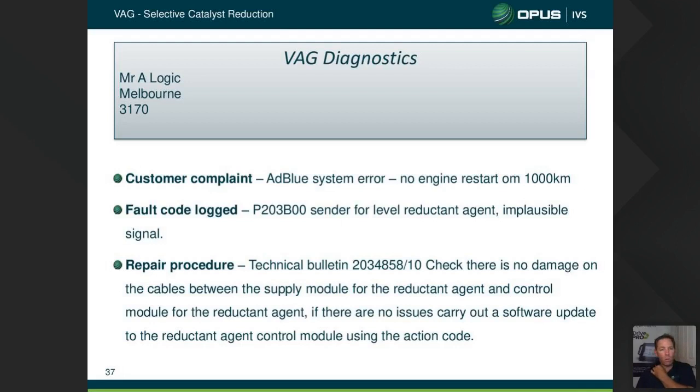Check for damage to the wiring. Again, because it's an implausible signal, don't just do a visual on the wiring. Unplug it. Look for water ingress or moisture ingress. Look for corrosion. Again, just make sure that terminal tension is correct.